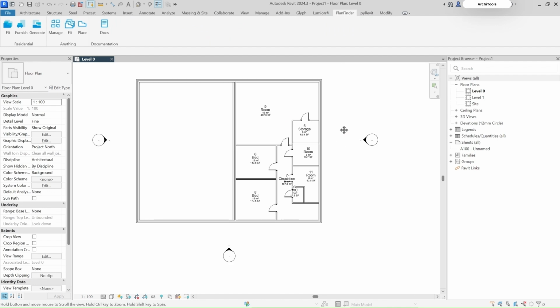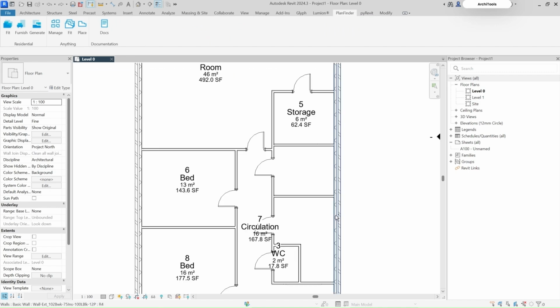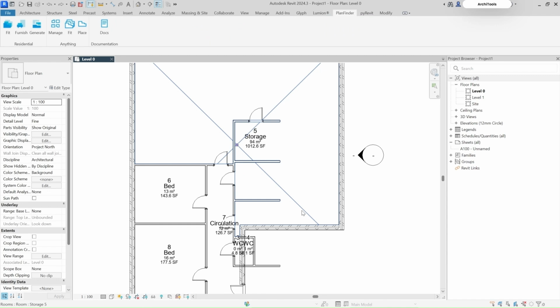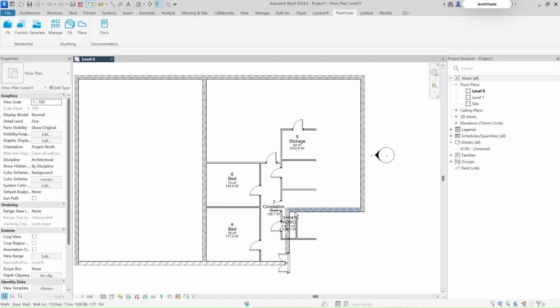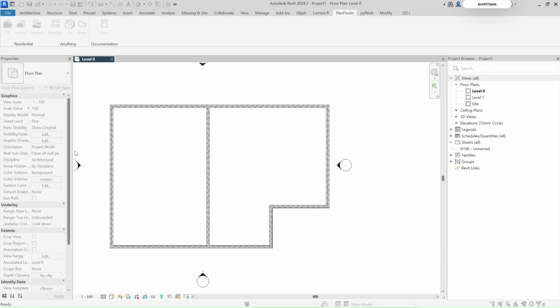So in order to avoid the error we had in the previous attempt, if I just press undo, this is what we had, which is not as per the boundary wall we have created. In order to work on the boundary wall and constrain a layout inside it, we can use this generate option. Just press on generate and it will ask for the point surrounded by the walls. I'll select this point, and next it will ask for get facades. Let's select this as facade and hit the finish icon.